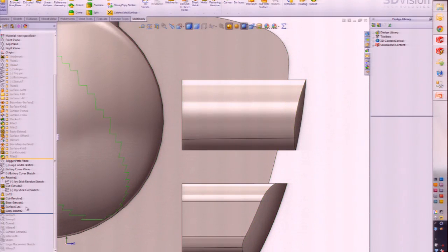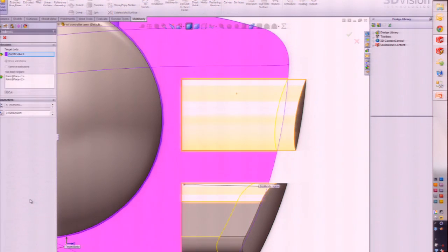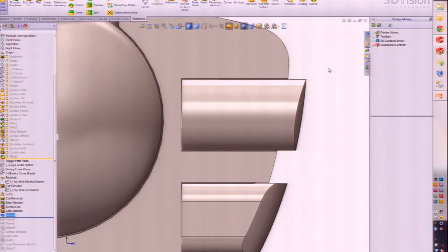They're overlapping, they're interfering. The indent feature that I showed you before, this is a little bit more visual now. If we take a look at that, somebody asked about clearance. So what it's doing is it's removing the common geometry between the 2. And right here, I can insert a clearance value as well, so it offsets while it cuts. So also very, very powerful.